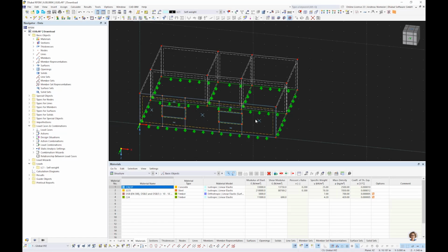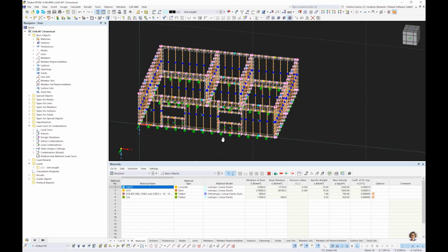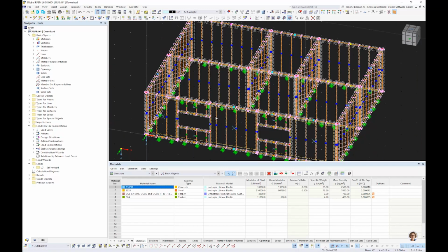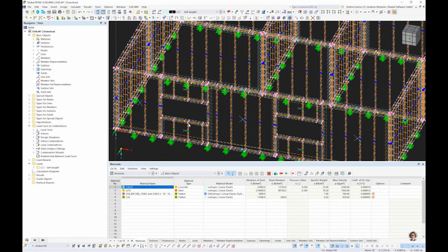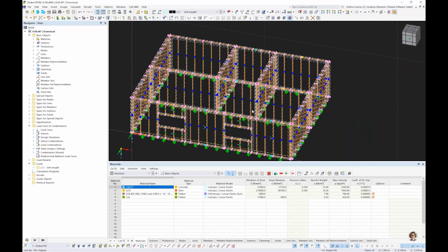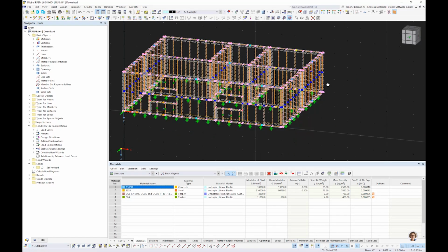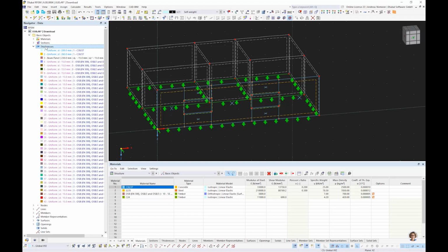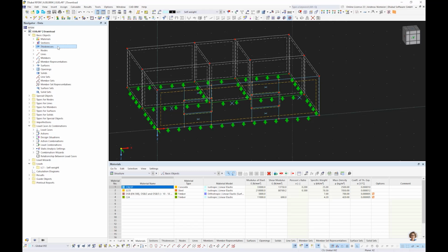And if I do this, the program is able to consider also windows with, let's say, a beam above and below, and also take care about the right distance of the vertical members. So it can really be a time saver, and you only define a few surfaces with a specific thickness type. Yeah. So this is one story of substructures.